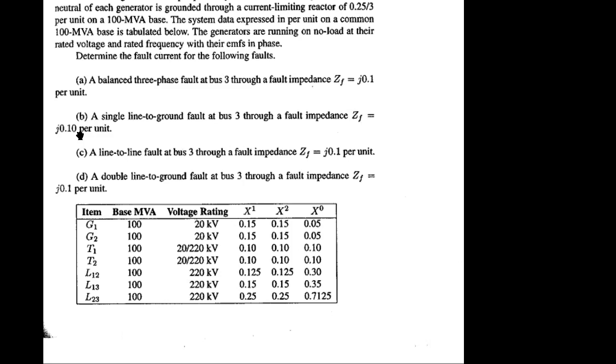That problem can be solved based on another approach, the ZBus building algorithm as well. That means your ZBus information will be given to you, and from that you can find the same solution for determination of fault current, bus voltage, and line current, these three pieces of information. So ZBus you can determine two ways, right?